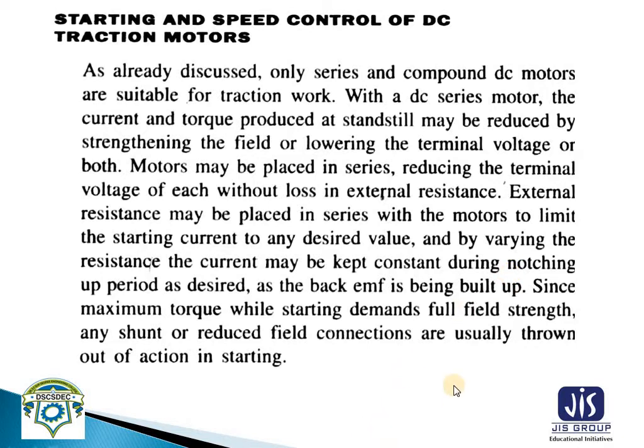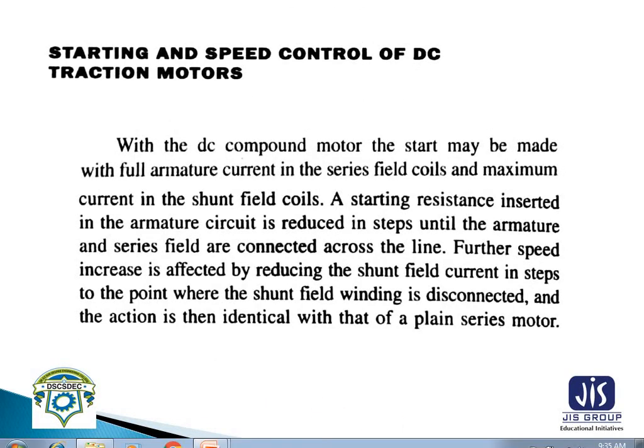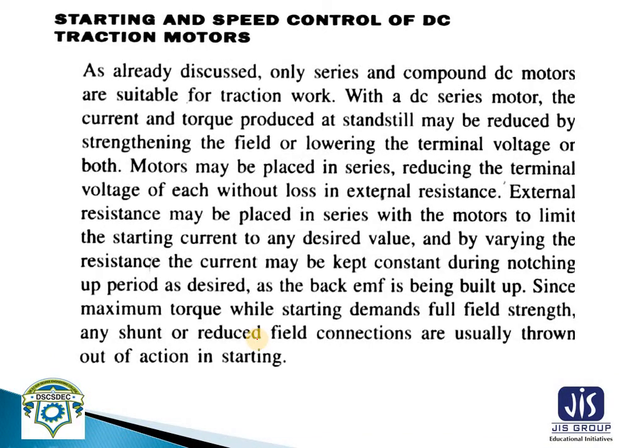As we have discussed previously, only DC series motors and compound motors are most suitable for traction purposes. With a DC series motor, the current and torque produced at standstill may be reduced by changing the field or lowering the terminal voltage, or both combined.